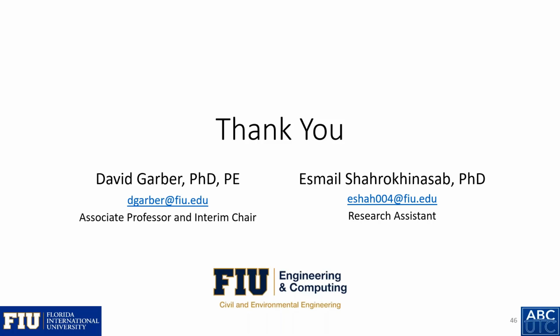Okay. How would someone actually come up with a UHPC mix design? Yeah, I think Dr. Floyd covered this in the previous presentation, but the starting point would be looking at all the work that's been done by previous researchers. So getting basic proportions from either our work or the many other research works that have been done throughout the U.S., and then looking at the specific material properties for your region or location. Then from there, doing the initial small batches to look at compressive strengths, and then sizing up to also look at the tensile strengths.